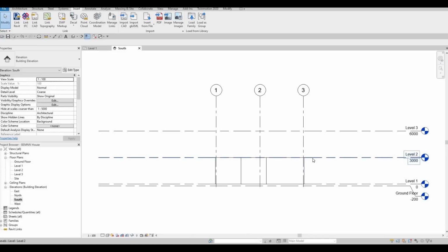So we're gonna make the thickness as 200, so it will go down 200, and I just want our entertainment system to be exactly at the 2800. So 3000 total height minus the 200 of the floor. So that's about at the height of the floor to ceiling.